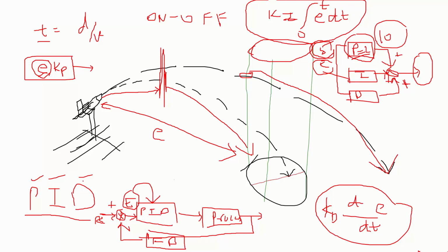So what the derivative controller does is try to oppose the rate of change of the motion that the missile will have. Since the rate at which the missile closes in on the target will be quite high, this gives rise to larger magnitudes of the derivative output. The larger the speed of the missile approaching the target, the larger will be the output from the derivative block, which means that it will reduce the speed at higher rates.